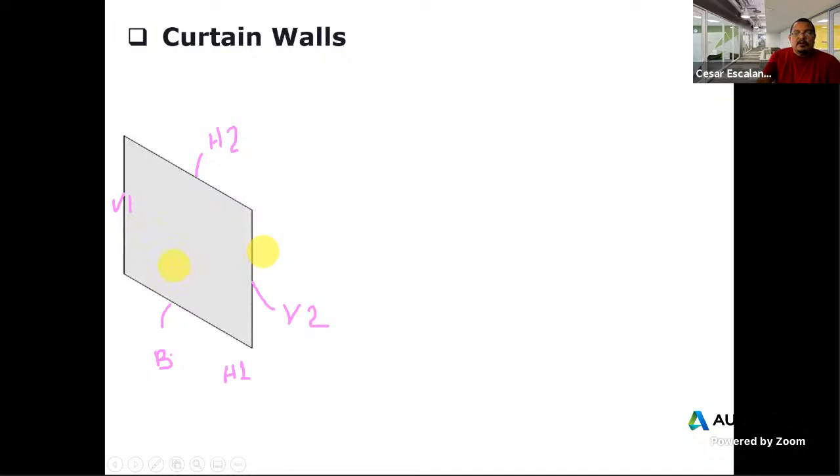And the order of vertical 1 and vertical 2 is the order in the creation of a wall. So if a wall is created using 2 points, the first point is the vertical 1, the second one is vertical 2. Border 1 and border 2, that's how it's called. Horizontal border 1, horizontal border 2, vertical border 1, vertical border 2.